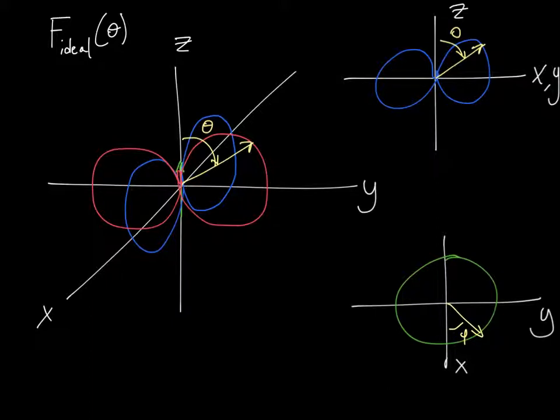So here we have the radiation pattern for the ideal dipole in the far field region, the Fraunhofer region. And it's only showing the angular dependence. So this pattern multiplies the space factor to get the full pattern factor. This ideal pattern has azimuthal symmetry, though I've only shown two planes in the three-dimensional drawing.